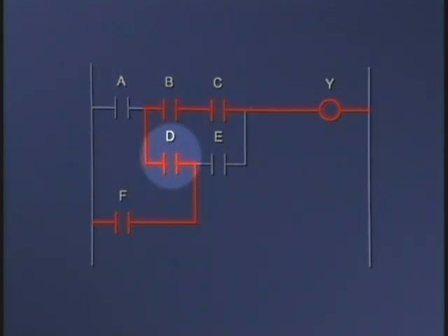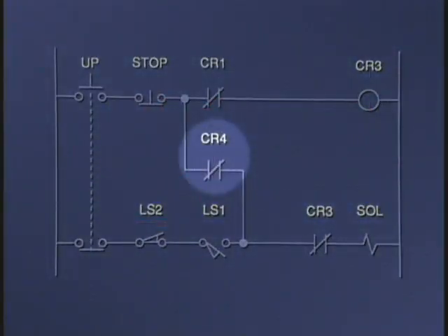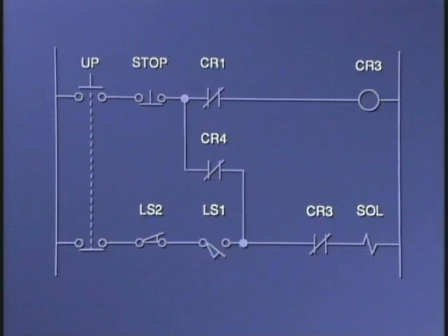Reverse power flow is not allowed in PLCs, primarily to prevent possible sneak paths that could occur in hardwired electromechanical relay systems. If you want reverse power flow conditions to be present, then you'll have to program those conditions in your rung using a forward path.